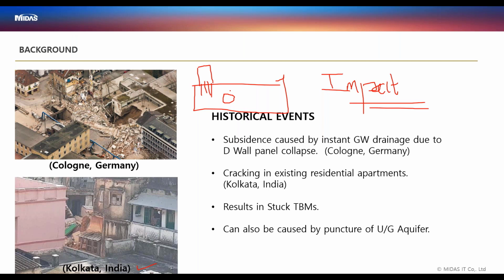If you do not consider the proper soil properties, and if you don't carry out the impact of the excavation onto the existing structure, and the seepage analysis, sometimes what might happen is the soil that is coming in between might get overstressed, and this might result in collapse of this building. So there are already examples.